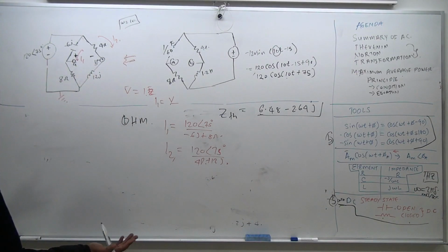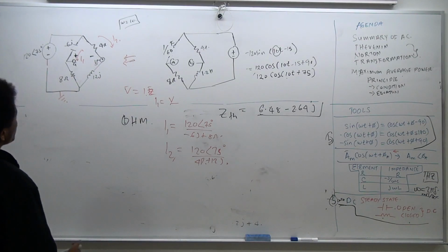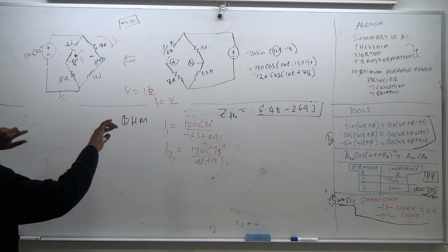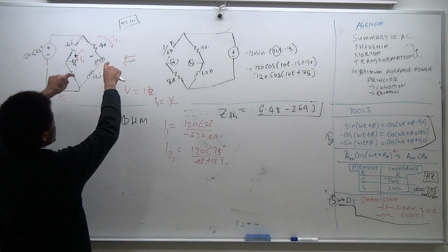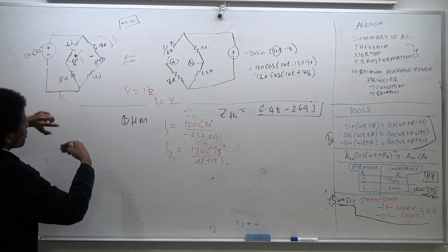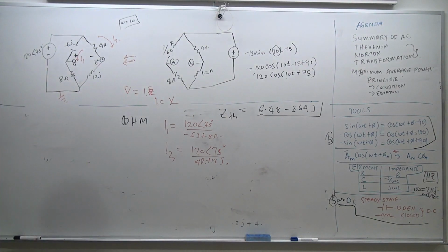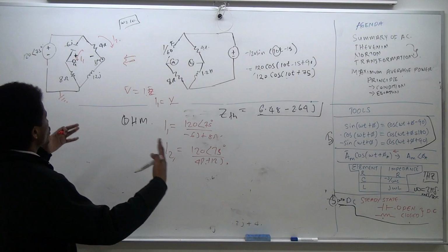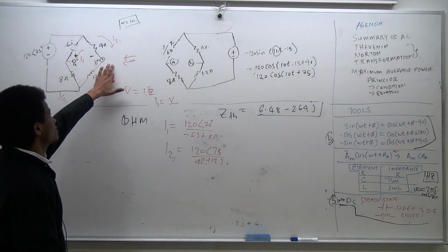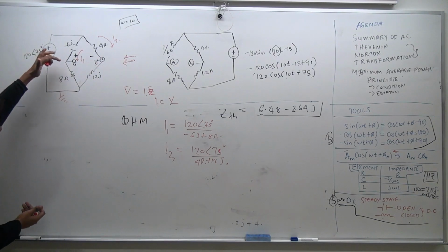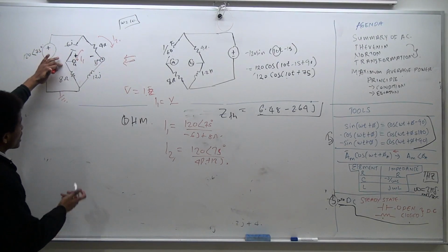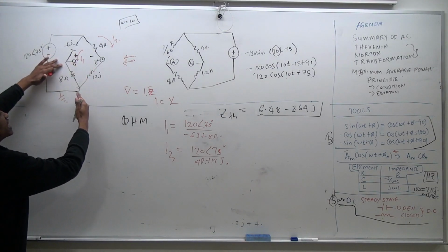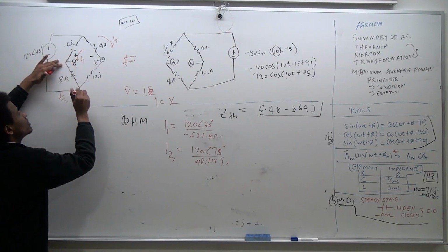You realize when you're finding the Thevenin voltage, it's just like finding the regular voltage, but the only difference is usually the voltage terminals or injection points could be very far from each other. So you're basically applying KCL or KVL twice, because you're finding a voltage at two different places. In this case, the voltage at terminal A can be found very easily by taking the current that flows through here and stepping it up. So basically, the current times 8 ohm will give me the voltage relative to 0.